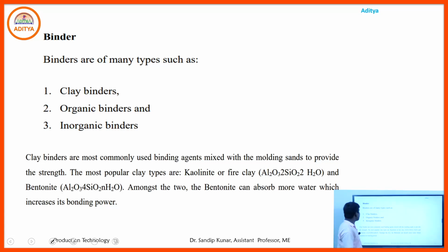Now, binders are of many types. Generally, there may be clay binders, organic binders, or inorganic binders. Generally, clay binders are mixed with the binding agents, which means they will be mixed with the molding sand, so as to increase the strength of that particular molding sand.